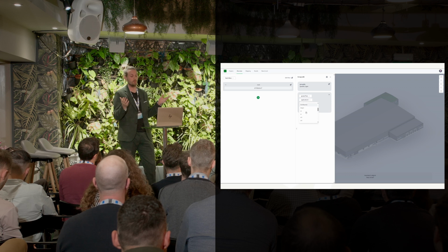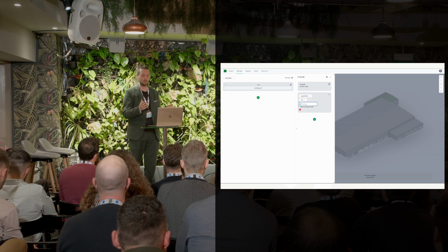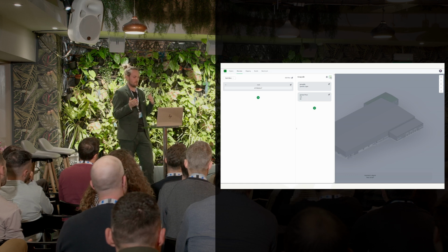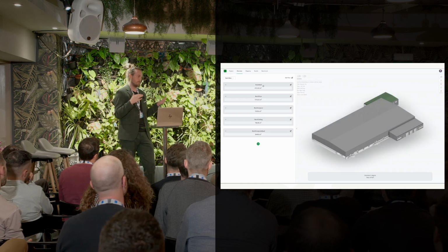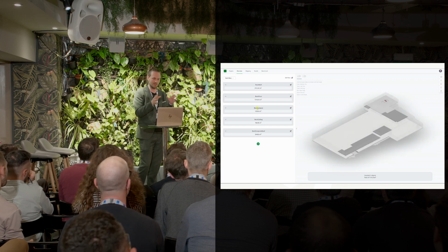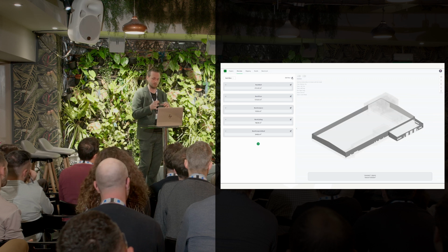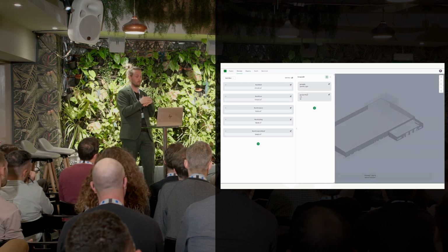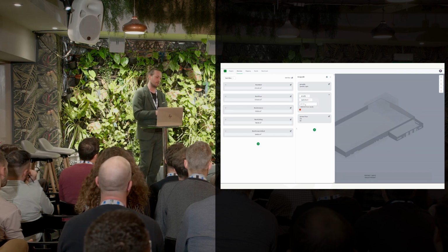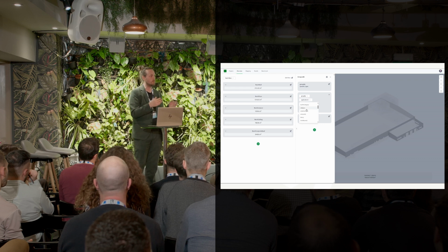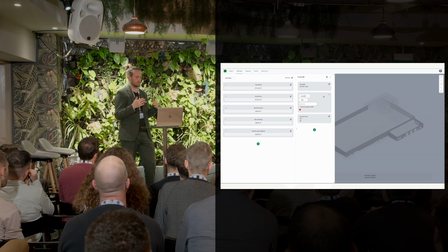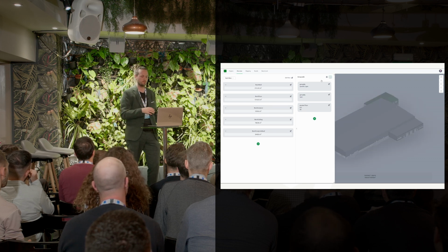So let's say it's a brown color of the object, and you know it's a wood object, depending on what phase you're in. So we're creating these kind of filterings to create a tree structure. This filters is already in Speckle from the start. But if you want multiple levels, or if you want to exclude something that has an area of 50 or above, or that doesn't have a square meter, or it's equal to some kind of ID, then you need to be able to create these smarter, more advanced tree structures.